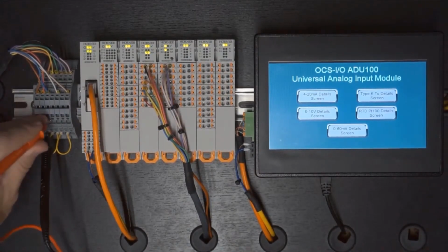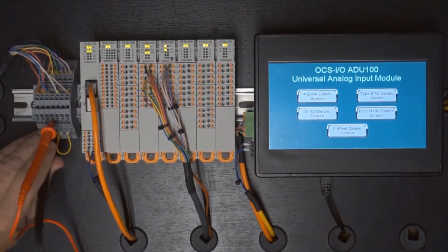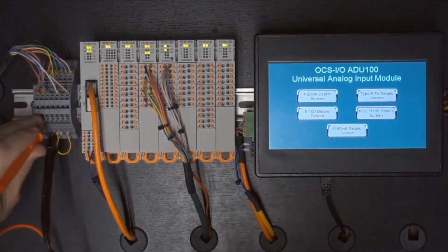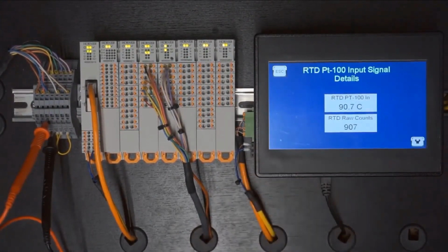So we disconnect our thermocouple probe here, and we change the simulator from thermocouple to RTD, which we have done. And we'll go with, say, a 50 degree setting, and we must remember to move our probes. Now we go to the RTD, and you can see that we've had a little trouble with our probes there, but we're making our way to 50. The reason it's taken so long is it was basically an open circuit, so it was at full range, and it's taken a while to get down close to 50.